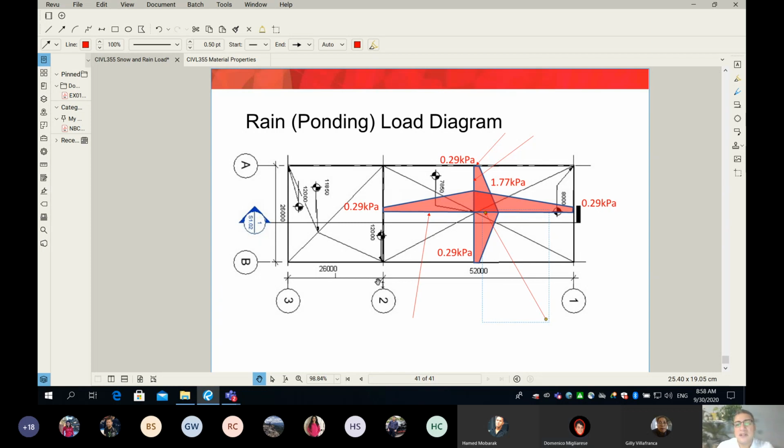But the scupper is added not for everyday drainage. Every day the water is going to go through the drain. The scupper is only for emergency, for the day where the drain is clogged, and then the water will go to the scupper. Does it make sense? Yeah, that makes sense. So it's kind of an emergency, a second or emergency exit for water.